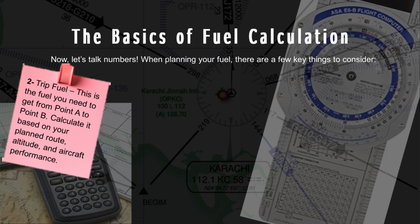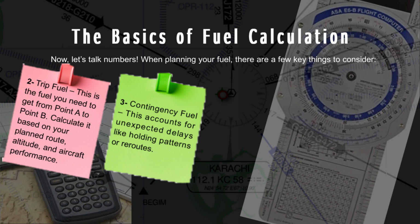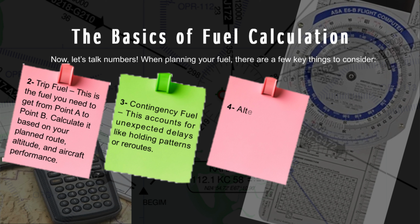3. Contingency fuel. Extra fuel added to account for unexpected deviations such as weather, air traffic delays, or route changes. Typically a percentage of trip fuel, e.g. 5%, or a specific fixed value per regulations. 4. Alternate fuel. Fuel required to divert to an alternate airport if landing at the primary destination is not possible. Includes fuel for climb, cruise, descent, and landing at the alternate airport.